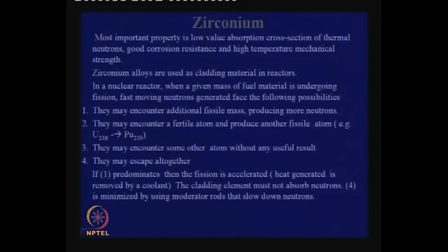Also, zirconium is ideal because it retains strength at high temperature, not pure zirconium, but zirconium alloys. It will have high temperature resistance. It will be able to withstand irradiation. It will not be corroded, and so there are many advantages.